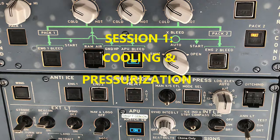Now that was what you can expect to see on the ECAM bleed page. But what about the ECAM cond page? What can you expect to see here? Think about the zone controller. That's a big one right there. So with the zone controller, you're going to have things related to that: the cabin fan, duct temperature, the aft cargo compartment, and related components are going to be indicating on the cond page.